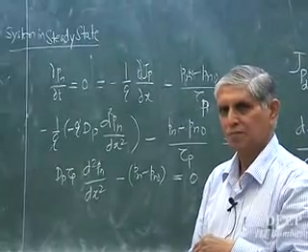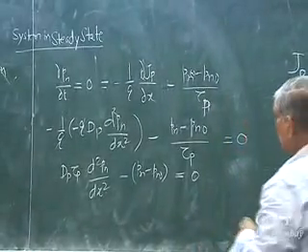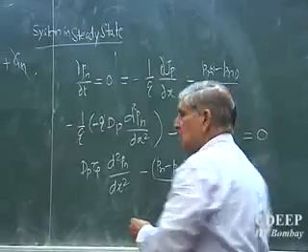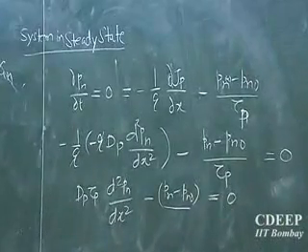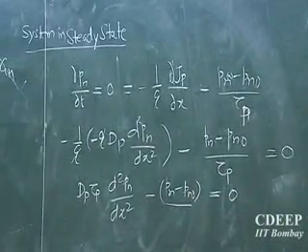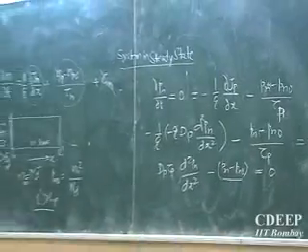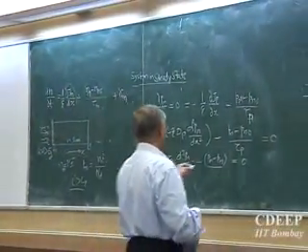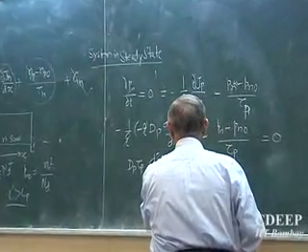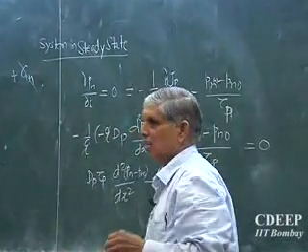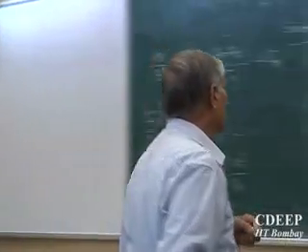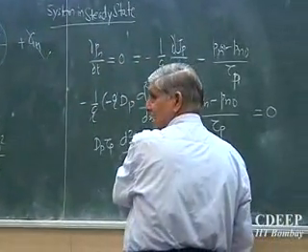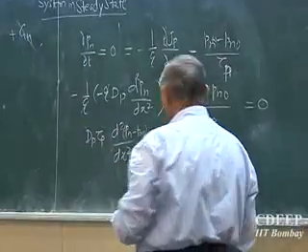Is it okay? What is Pn minus Pno? At any instant of x, Pn minus Pno represents what? Excess carriers. Pno is the equilibrium value. How many above? If I differentiate this, they are the same, because Pno anyway is constant. So now, if I do this, then our equation is simple. I call this delta, I call this delta, and then start solving.